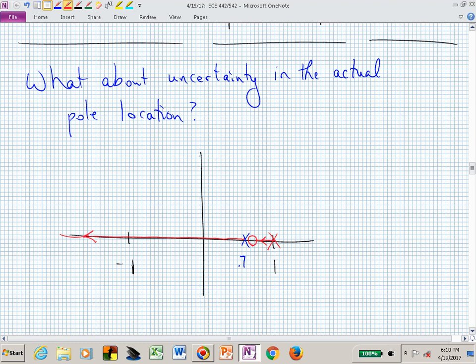So the gain that you've picked to produce this speed of response, now how many branches of the root locus do you have? 2. How many closed loop poles do you have? 2. You had 2 before. 1 just got ideally canceled. But now if we crank up the gain to what we had before, this pole is going to be right there. It's almost canceled by the 0 of our controller, and this one should be close to where we put it, which was 1/2 before.